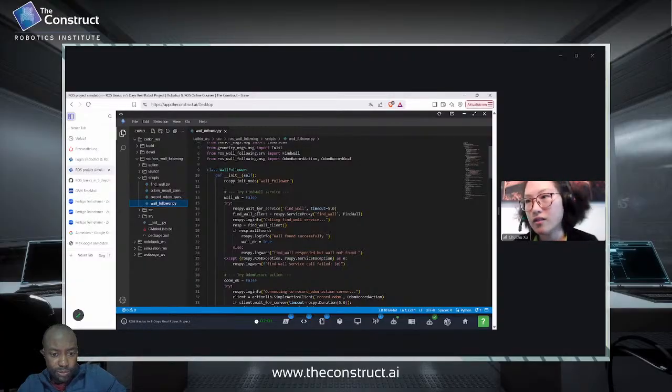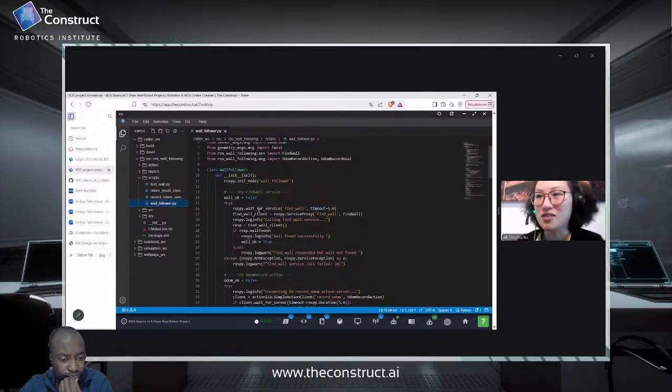It's implementing what the assignment required: the find wall service is called first, then the odom recording is called second, and after it's called and succeeds, it starts to follow the wall. But even if it failed, like in our case, where it fails to find the wall, it will just start the main loop of following the wall. It will recognize anything on the right-hand side as well, and do error handling when something is quite odd. Obstacle, sharp left, obstacle, sharp left, and somehow it works. All right, I get that.